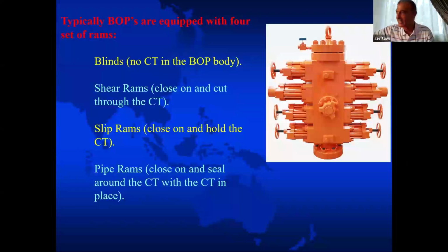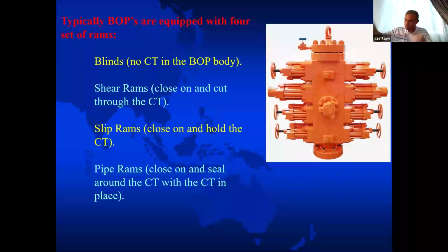Below that is the cutter blade, the cutter rack. These are the cutters, two pieces. So when you close, this is your pipe, so it cuts your pipe. This is as per the API. You use it once only. Although it can cut up to 30 times, this is the factor of safety we are using. One time use only. If you use it to cut a pipe, kiss it goodbye, fellas.